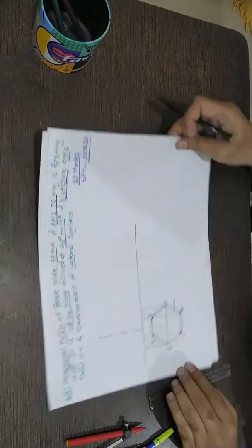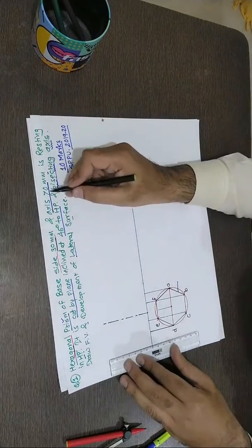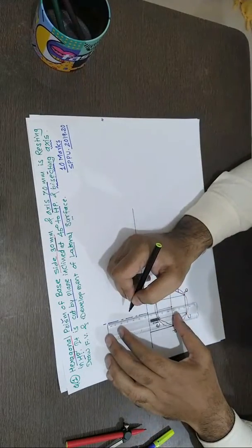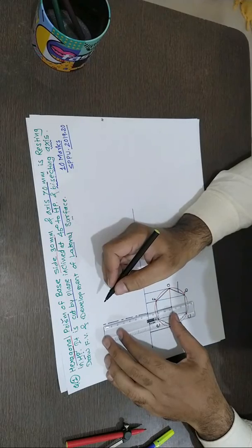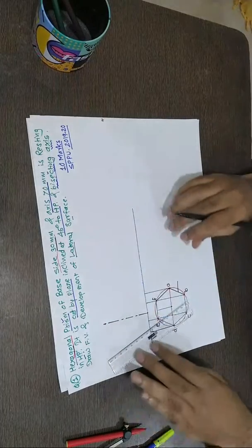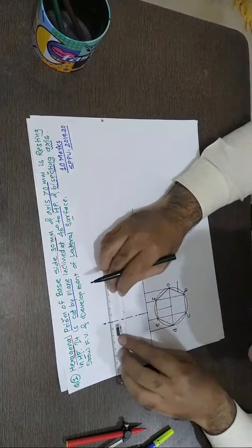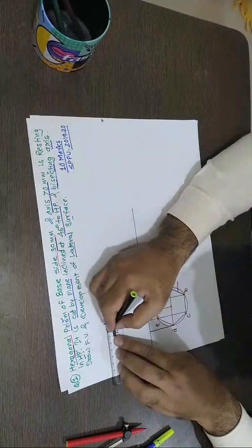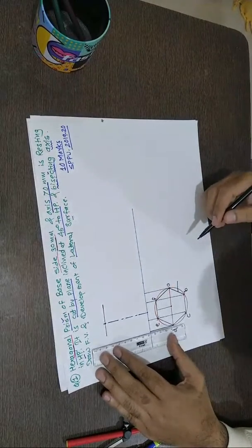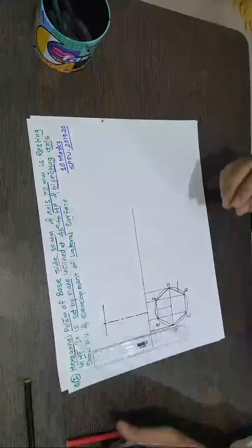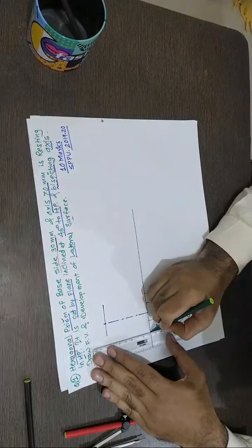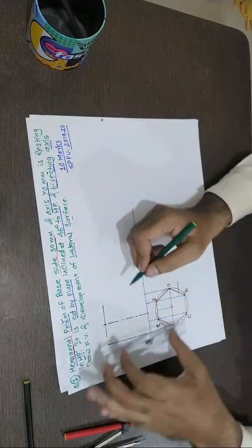Now I'll draw this front view with the axis at 70 mm. So I'll mark a 70 mm distance on the axis. As it is a prism, no problem, it's very logical. This is a point, and this is the 70 mm point. So what I'll do is draw one reference line exactly parallel. I don't have an eraser for the sketch pen, of course, so I'm drawing very precisely. This should be the height of 70 mm. So draw the front view.